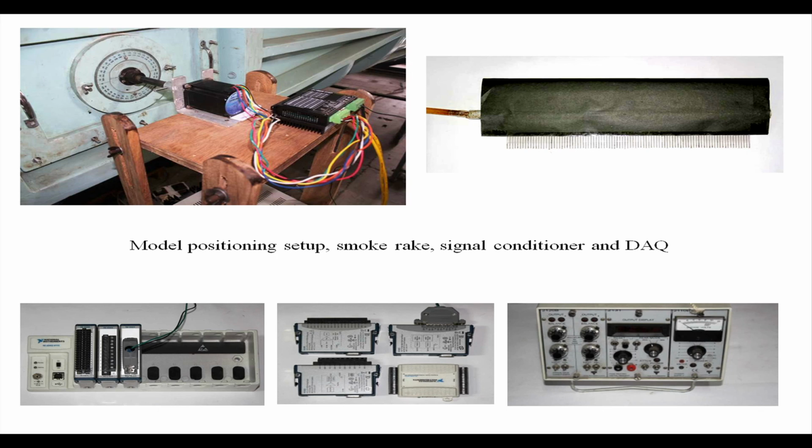And the other part of it is, as I was telling earlier, that we are not doing the experiment in such a manner that the angle of attack of the airfoil is changing continuously. We are fixing it at an angle of attack, taking the measurements, then moving to the other angle of attack, again letting the flow reach another state of equilibrium, then acquiring the data, not acquiring the data in a transient sense. That is basically the difference between say a static and a dynamic situation. But later in one of my lectures, I will explain a little bit more on the dynamic characteristics, which is equally relevant today because of numerous applications.